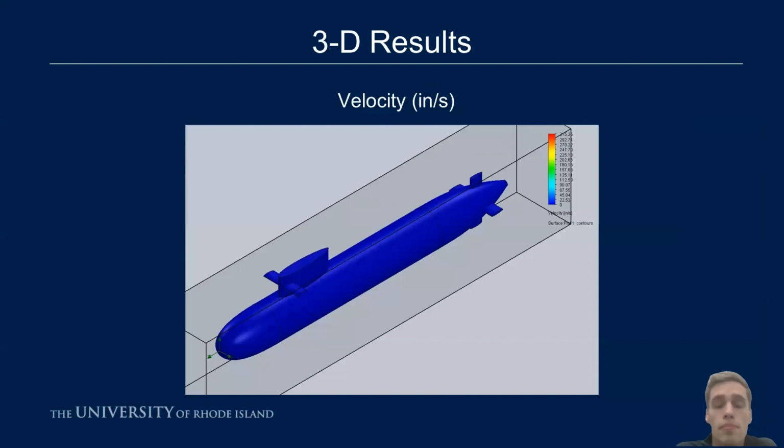Now, that becomes interrelated on our first 3D plot, which is a surface contour plot, in this case of velocity. Upon inspection, you'll be able to see that the entire surface of the submarine has a velocity of 0. This is due to the no-slip condition, which is applied in the simulation. It's an idea that we use in fluid mechanics in order to run calculations, to say that fluid is not simply slipping across an object, that there's some friction there, and that there's no slipping.